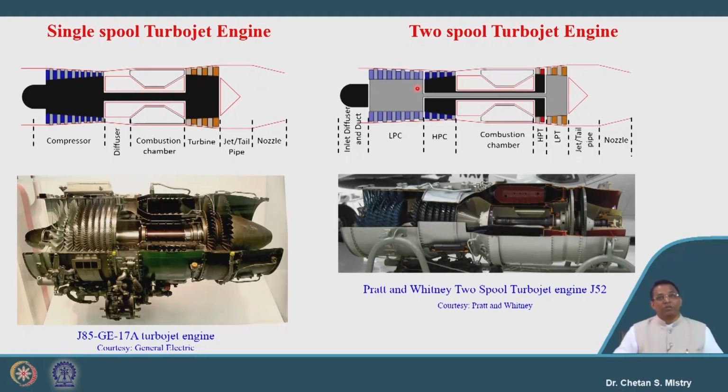Why do we rotate at low speed? We have discussed that in terms of our limitations with shock formation. Why do we move to high speed? That also we have discussed, in order to reduce the number of stages. So, I am sure you are aware of all these things. Now, you are confident about the single spool configuration and the two spool configuration.